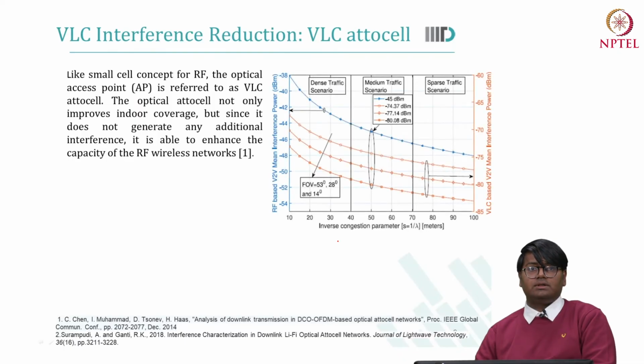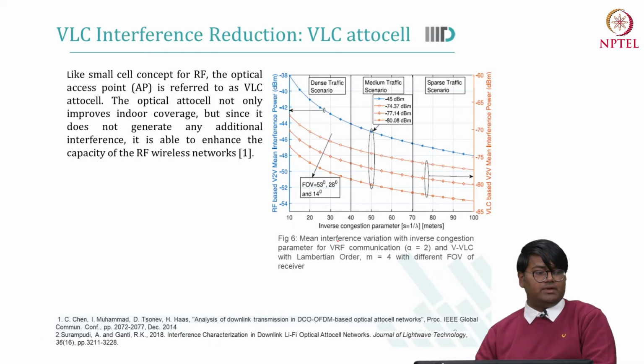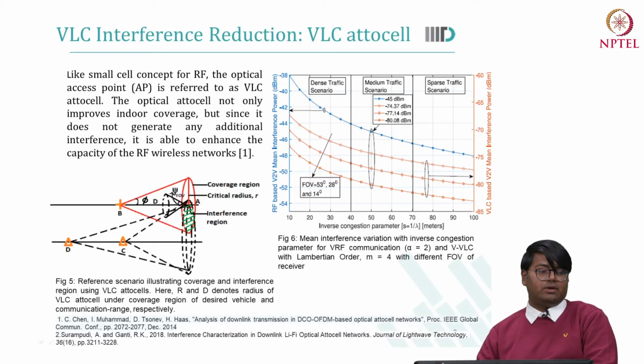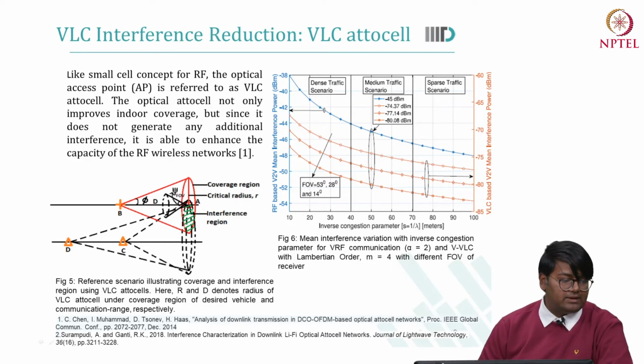Depending upon the simulation parameter settings, now we see the simulation results for average optical interference and the effect of reducing the FOV on average interference power in case of vehicular VLC. Typically, the received signal as well as the interference model considers a full FOV of 180 degrees at the PD receiver, which leads to a worst case bound on the interference.